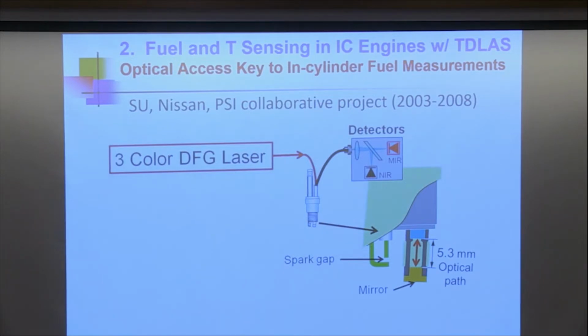So fiber comes down through here, and then there's a little metal reflector, separated by 5 millimeters. So that means a 5 millimeter optical path, 10 millimeter round trip. And it's just a low quality mirror. It's a little metal mirror. The mirror would get dirty, we'd have to polish it back up. But all you need is some light to come back.